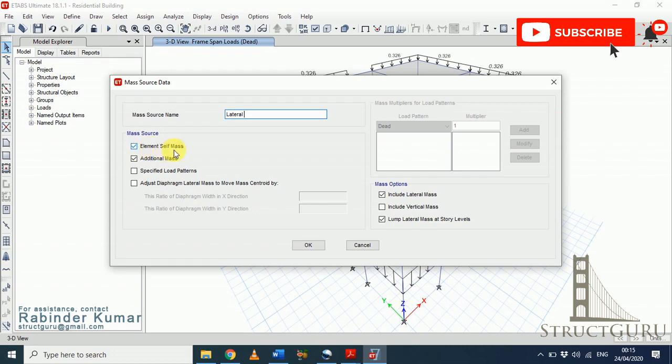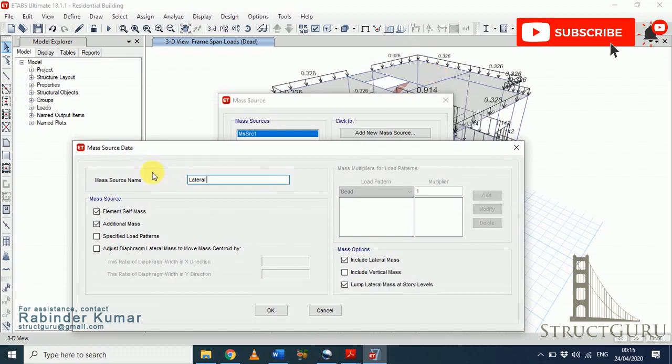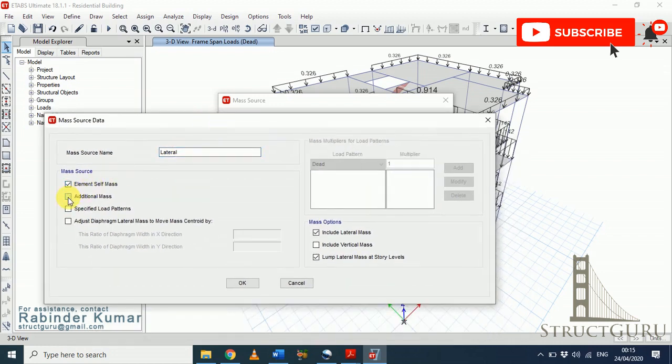As you can see, there are 4 checklist parameters, so I will explain them one by one. Number 1 is element self mass, that means all the self weight of the structure. So that should be included, so yes, check it. Next is additional mass. Any additional mass you want to include in the mass source, you have to check this parameter. The third option is specified load patterns. That means you have to specify the load patterns yourself, referring to the code books. If you are referring to Indian standards, you have to refer to Indian code books. If you are referring to any other country's building codes, you have to put the values accordingly.